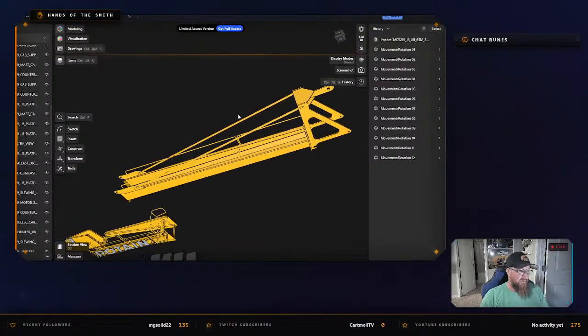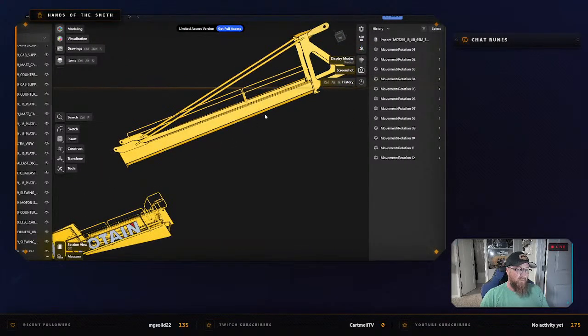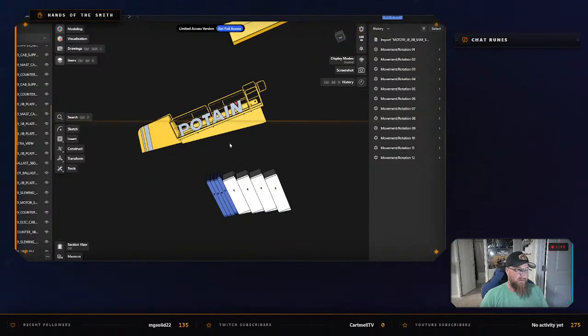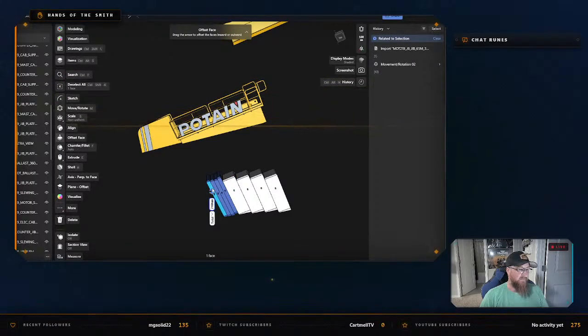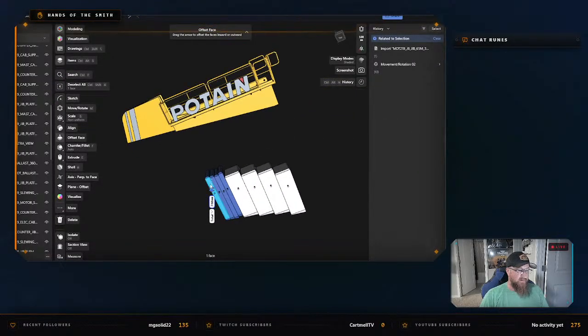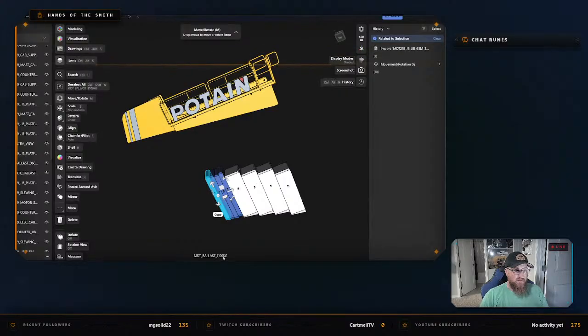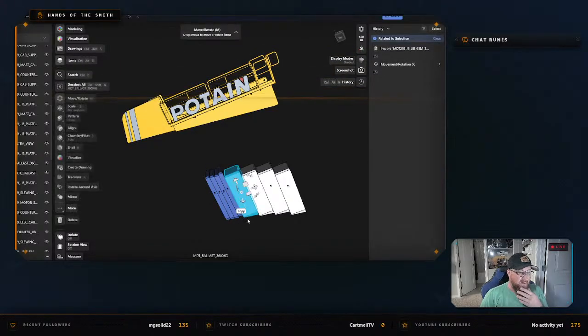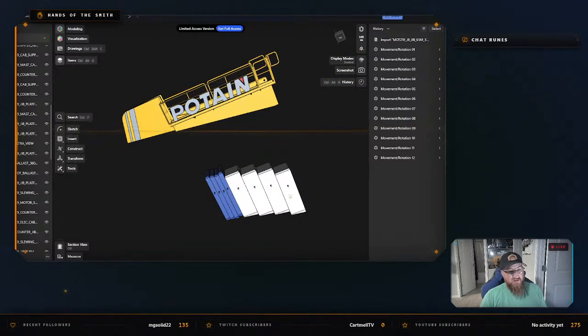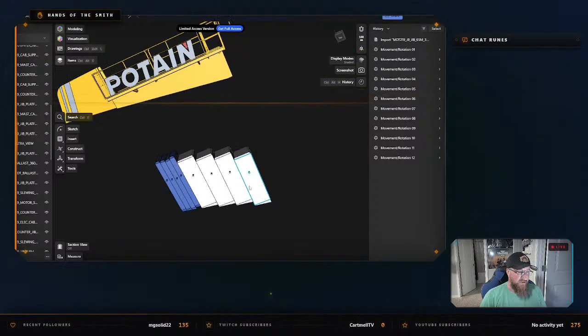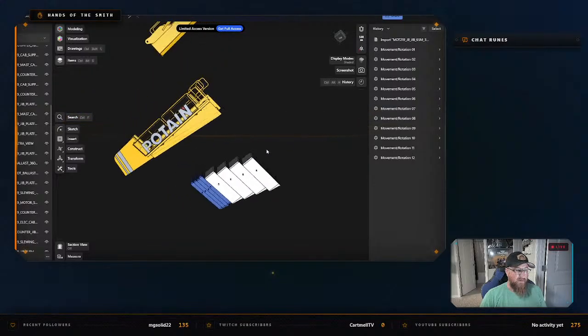But yeah, so here's one part of the counter jib. Obviously, the last part of the counter jib with the wind sail, the various ballasts. So you can see that this one here is the 1100 kg one. This one here is a 3600 kg one. So if you're going to have 213 feet of jib, you would need all this counterweight installed.